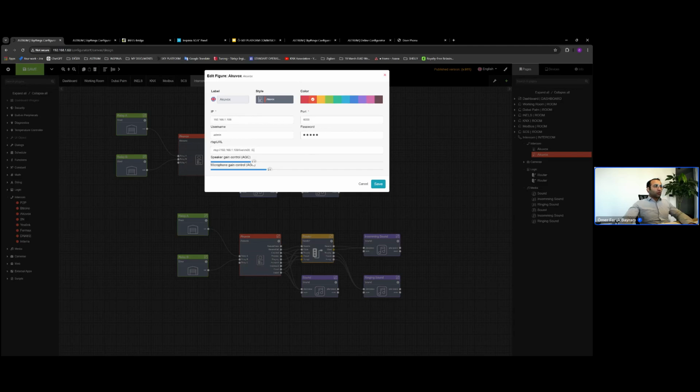Okay, so like we said, if you have external camera for this outdoor unit, you can write this external camera's link to see on panel after receiving a call from outdoor unit. The image will come from this external link, or you can write here outdoor unit's own RTSP URL link. So in that case, when you receive a call, before answering it, you will be able to see image, and then you can answer it. Okay.